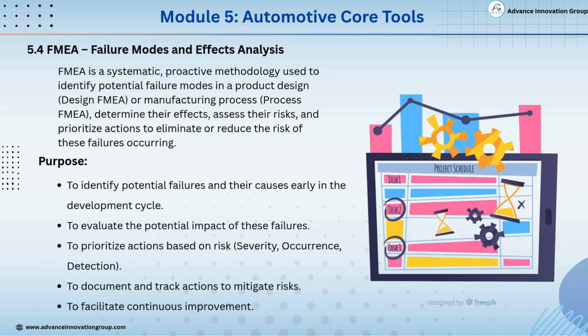This slide introduces FMEA, which stands for Failure Modes and Effects Analysis. FMEA is a proactive tool used to identify, evaluate, and reduce risks of failures, either in product design (DFMEA) or manufacturing processes (PFMEA). By analyzing potential failure modes, their effects and causes, we can take preventive actions before the failure actually happens.